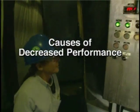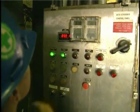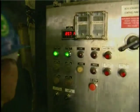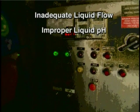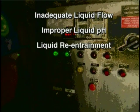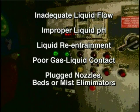There are several operating problems that can occur in wet scrubbing systems. The most common of these include the following: inadequate liquid flow, improper liquid pH, liquid reentrainment, poor gas-liquid contact, plugged nozzles, beds, or mist eliminators, and corrosion.